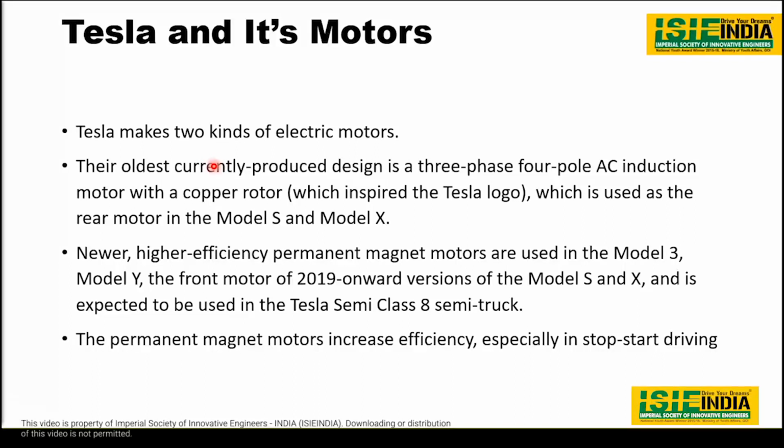So yes, Tesla Motors has a 4-pole AC induction motor, okay, with a copper rotor. Actually, they just give copper bus bars on the rotor side also. So there is no specific winding actually. They give copper slots and put the bars in, right? That actually inspired the logo, Tesla Motors' present logo, right? Model S, Model X are using these induction motors, right?